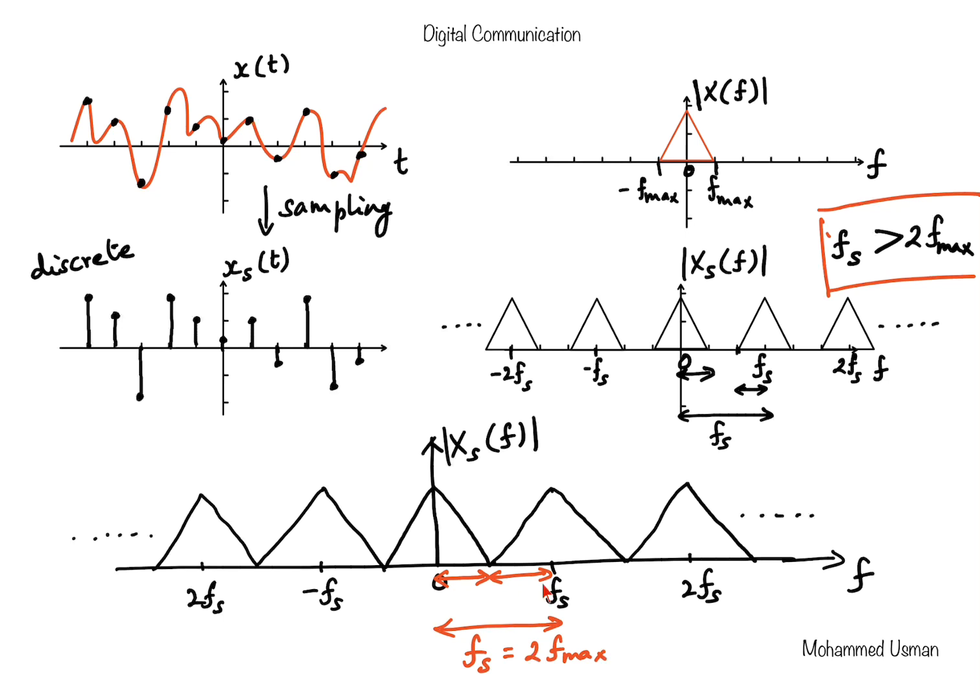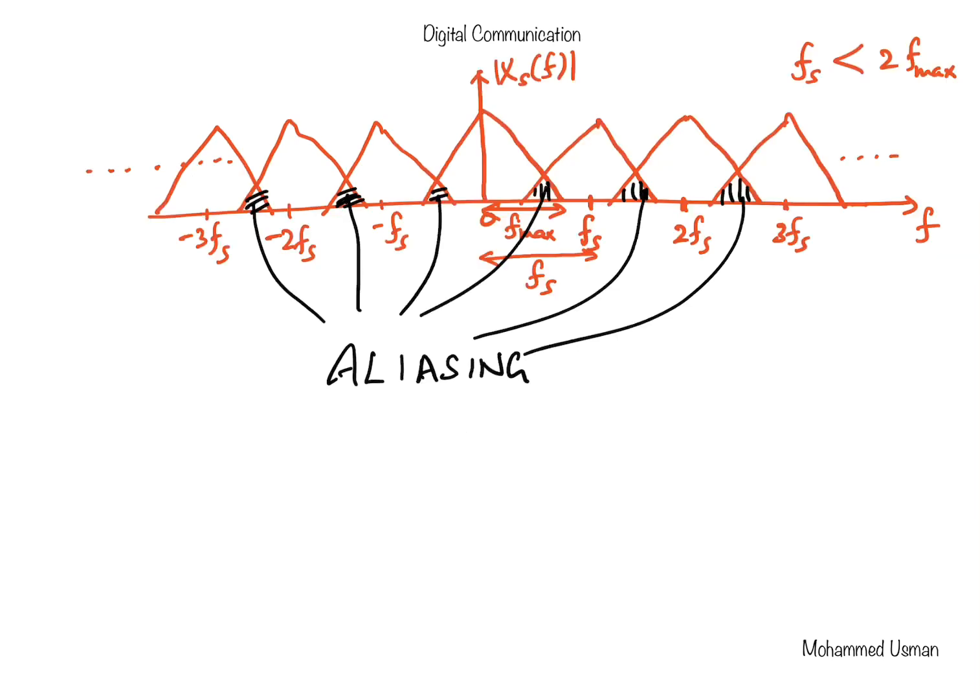But when the sampling rate is reduced below the Nyquist rate, these replicas move further inwards and overlap with the previous spectral replicas, causing what is called aliasing distortion, as we have depicted in this particular diagram. So aliasing occurs here, which is nothing but the mapping of higher frequencies onto some lower frequencies.